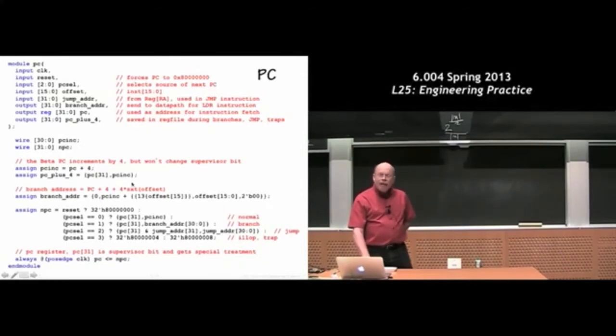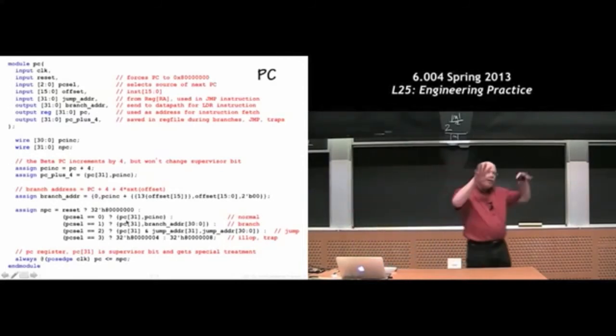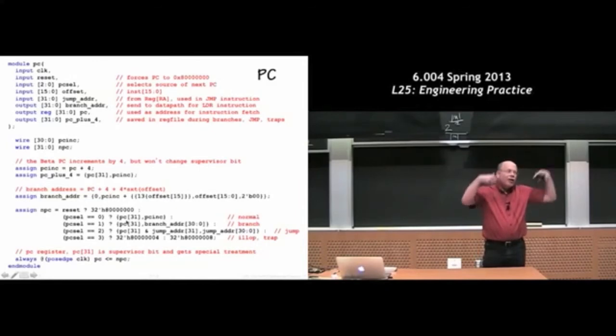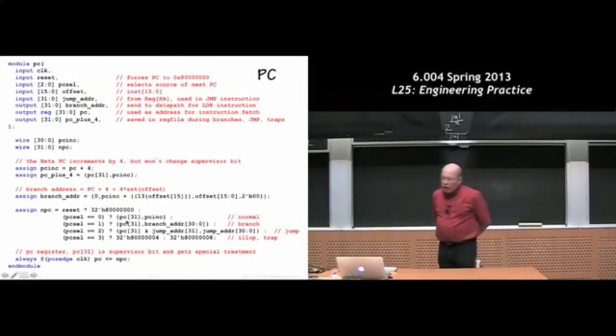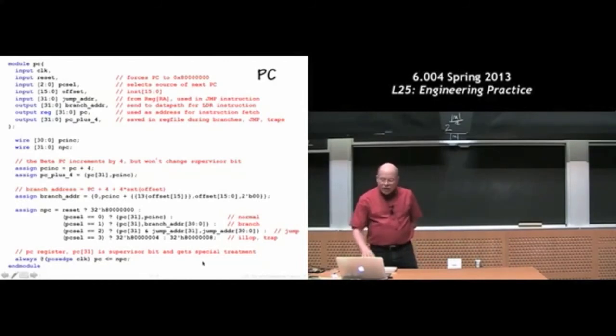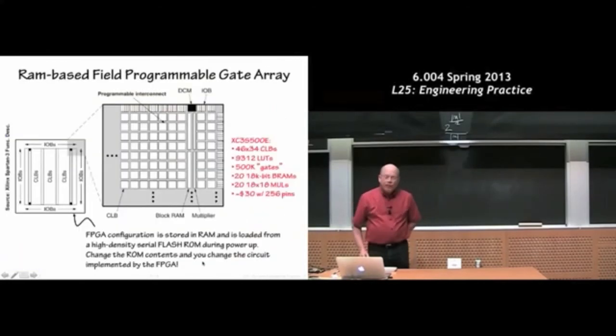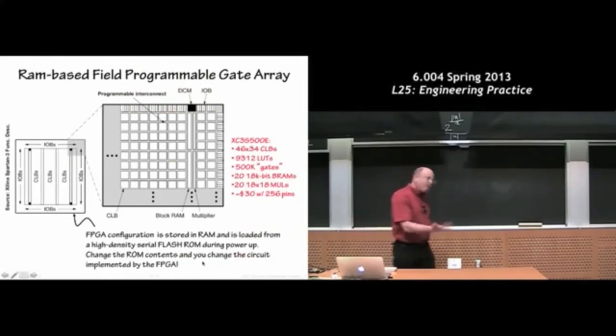These braces here are basically making a bundle of wires. So for example, this is saying, take the 31-bit PC Inc value, which I've described up above, and you can see over here it's a 31-bit value, and concatenate that with bit 31 of the old program counter, or IA31 in our parlance, to make a 32-bit PC value. So this is actually a fairly elegant notation, and again, my claim is that you would find it much easier to change the behavior of the program counter logic here than if you went back to your circuit. So what do we do with these descriptions?